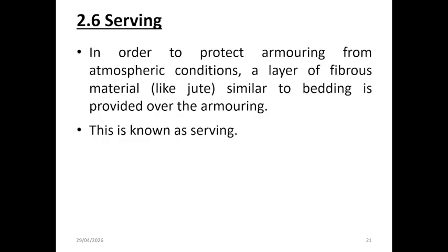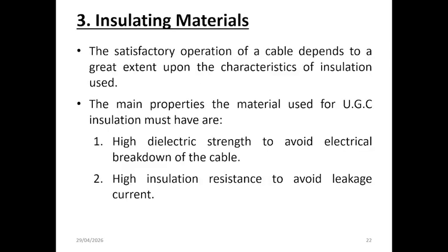All right. This slide explains the serving layer in underground cables. Serving is the outermost layer made of fibrous material such as jute applied over the armoring. So its main purpose is to protect the armoring from atmospheric conditions like moisture and corrosion, ensuring long-term durability of the cable.